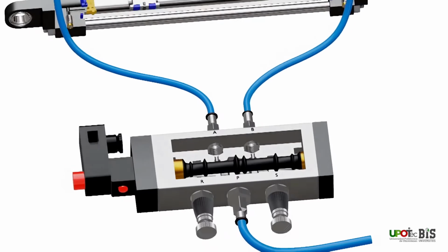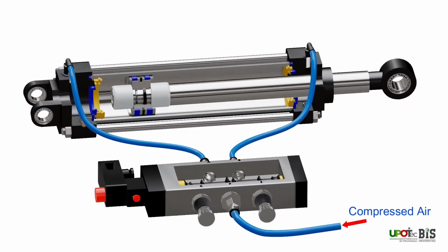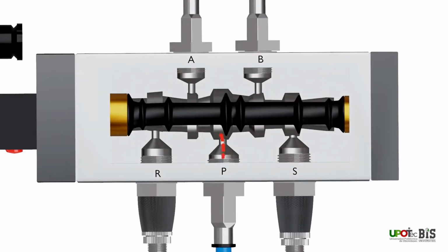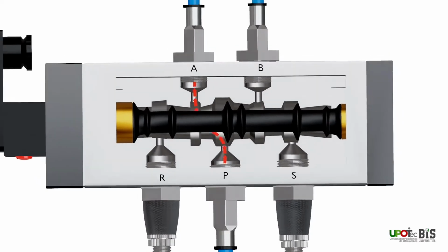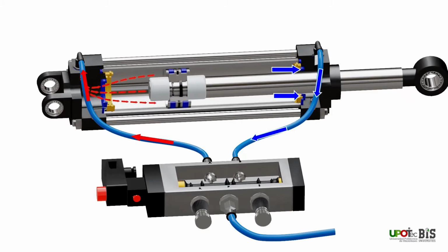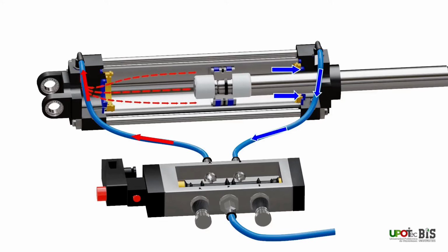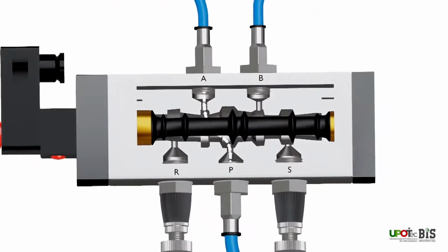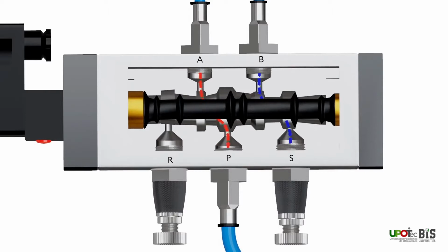Now let's understand how a pneumatic cylinder works. The compressed air is supplied through inlet port P of the valve. The valve directs air to a particular direction, which we can observe in the animation. In this case, the air is directed to port A. This high-pressure gas is then transferred to the cap end of cylinder through the pneumatic hose. This creates high pressure in the cap end of cylinder, which therefore pushes the piston towards the head end. This also pushes gas from the head end. This exhaust gas travels through the other hose and reaches the valve. The valve directs this gas towards port S and allows it to escape through a pneumatic muffler. The gas muffler helps to reduce any noise produced during exhaust.